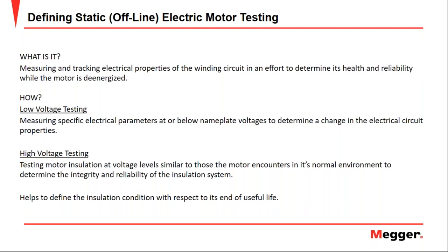So in those cases we have to do it from the MCC, but if a fault is detected by carrying out the test from the MCC, the problem could be either in the motor or in the power cable insulation. So we have to be very sure about the fault's location and how it's going to affect the whole system.